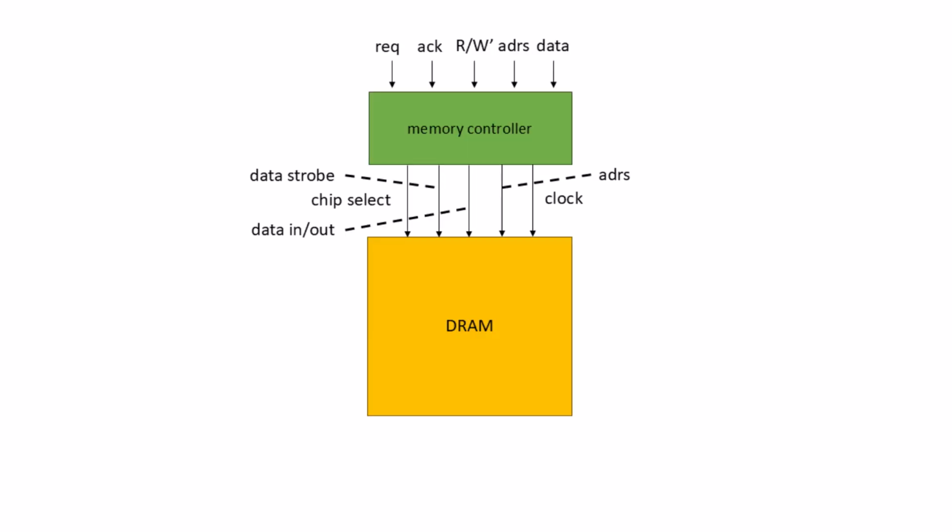A memory controller has two roles. It manages the parallelism in the DRAM to execute memory operations efficiently, and it manages the complex timing requirements of memories. Many memory controllers can accept several transactions. They'll try to order the transactions to most effectively use the memory. Memory controllers are also designed to provide the required timing. They can receive timing parameters from the DRAM devices in order to adjust their operation to what memory is installed.